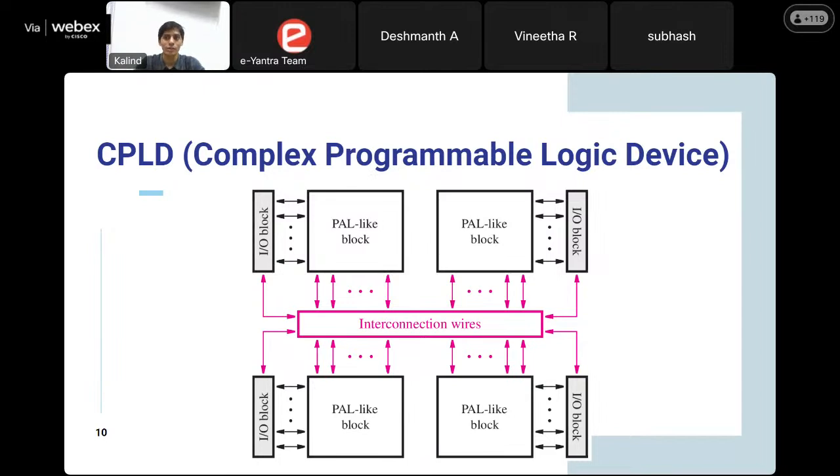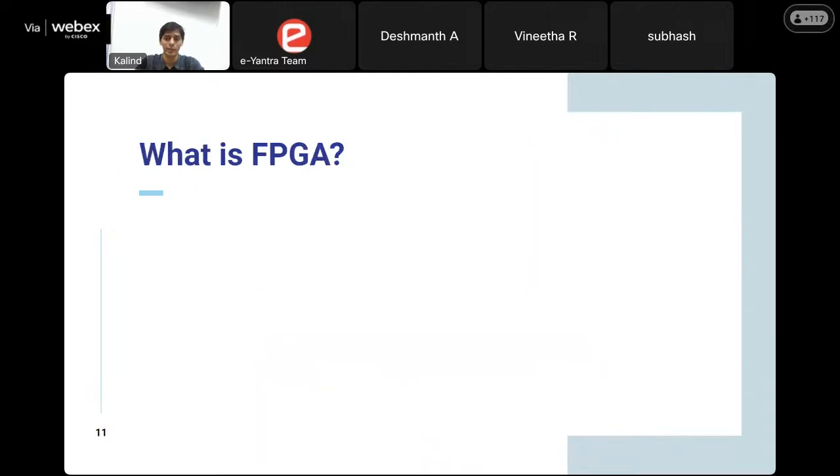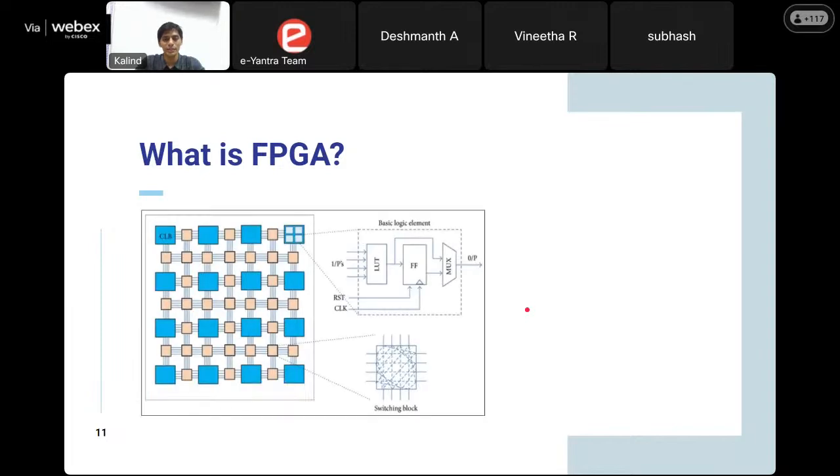But is that all? Is CPLD the best choice to design all kinds of logic circuitry? Again, the answer is no, and that's how the FPGA came into existence. In the case of FPGA, you do not have what the CPLDs or SPLDs have, like the pool of logic gates and then some programmable switches.